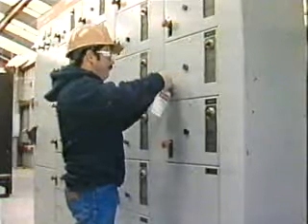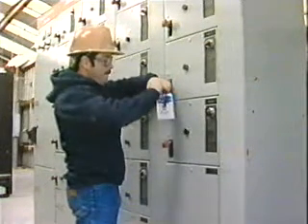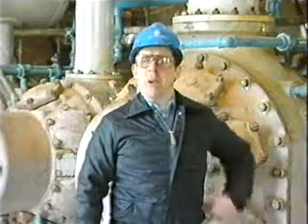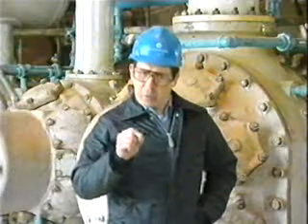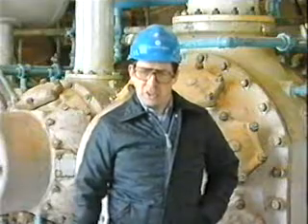Before any inspections of moving components are undertaken, the compressor package must be isolated from all power sources as outlined in your company's lockout-tagout procedures. Your student manual itemizes those elements that require attention during a periodic inspection. You should carefully study those things when you read this section.